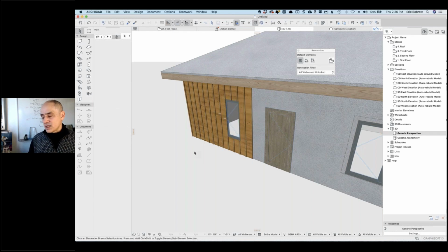Now, this is the only way, well, not the only way. You can't just use the wall tool and say, I have a profiled wall and get this, because profiles are what you see in a section and they get extruded. So if you have siding that's horizontal or board and batten that's running horizontally, then you can do that. But for vertical stuff, you need something that does like this.